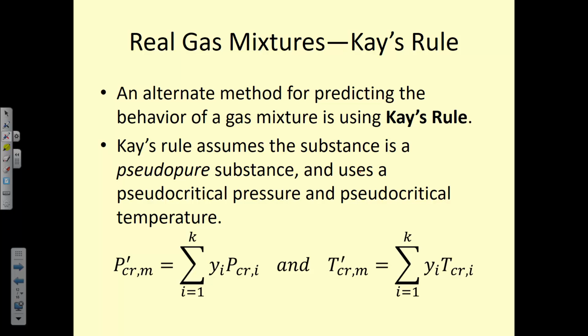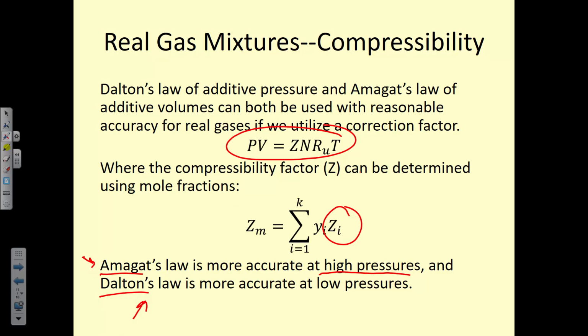How do we know what the pressure is that we would switch on? Is there a good number? No, and it will vary for every gas. But if you are just looking at your critical point pressures, in this table, A1, you can see, for ammonia, it's 11.28 megapascals. But for helium, it's 0.23 megapascals.